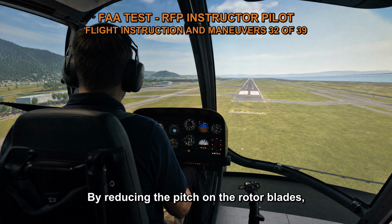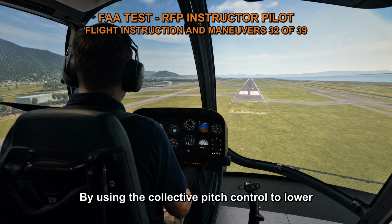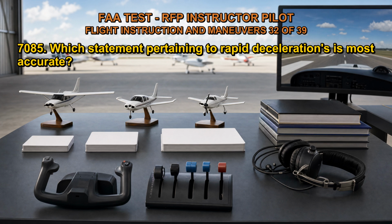By reducing the pitch on the rotor blades, the helicopter will descend and allow the downslope skid to make contact with the ground. By using the collective pitch control to lower the downslope skid to the ground, the pilot can achieve a stable and balanced landing on the slope.